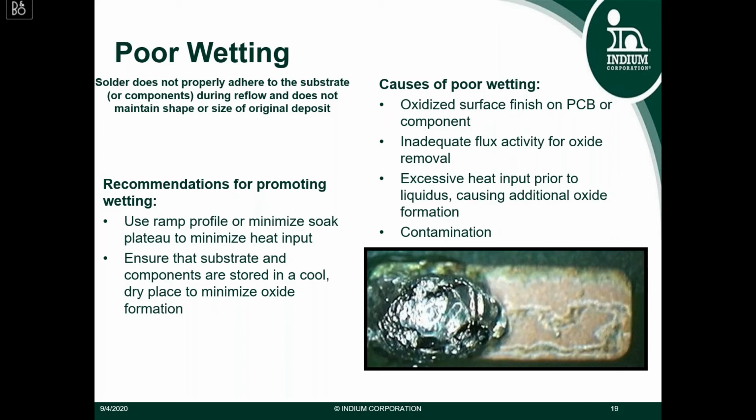Too much heat input prior to the solder melting, which will cause more oxide formation, thus more chances for non-wetting to occur. And then finally, contamination, fingerprints, lotions, or anything that you would consider contamination.